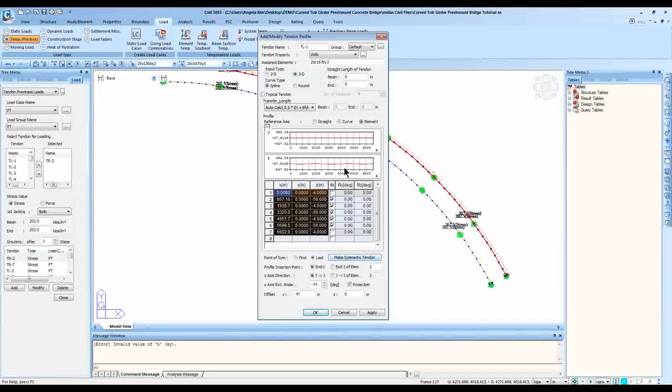Element, you just need to choose a group of elements and define the offset locations. Yes, X is the longitudinal, Z is literally the vertical, and Y is the transverse, correct? Yes. And this is what really makes it easy for a curved, irregular type of structure too.